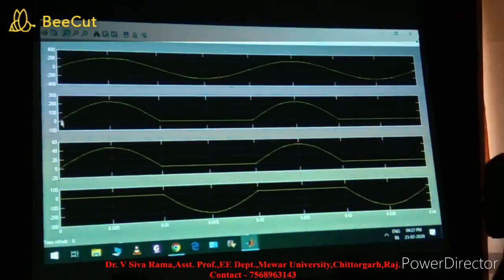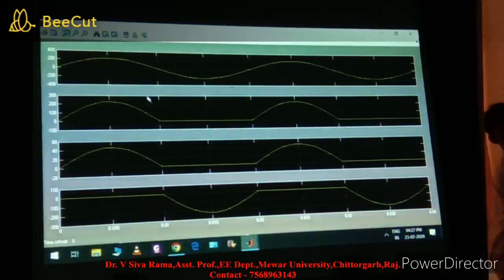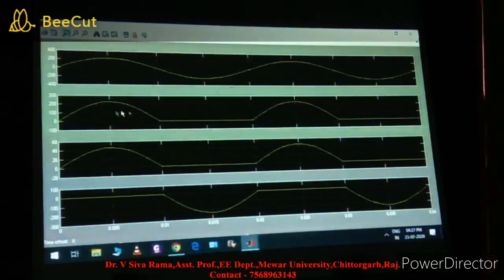Second one, if you see from the simulation diagram, V0, the diode will be on from this point to this point, because the voltage across the diode is positive, so it is forward biased. According to our shortcut, all the switches are ideal, so V input equals V output. Now from pi to 2 pi, the diode is reverse biased, so the output is 0.